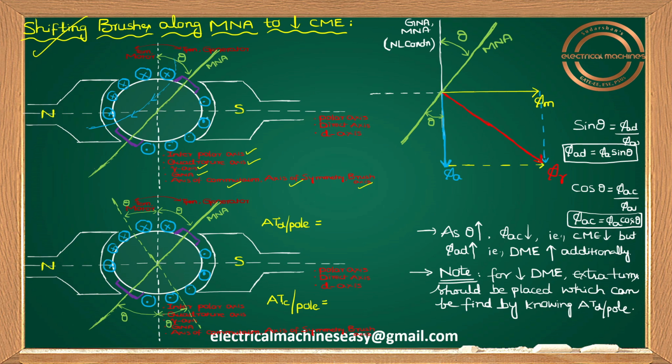And similarly here, the dot is the direction of armature current, which means out of the board. Your thumb should be out of the board. So now the curled fingers, the direction of armature flux, becomes anti-clockwise. It will be like this. I think it is clear, right? That's the direction of armature flux.